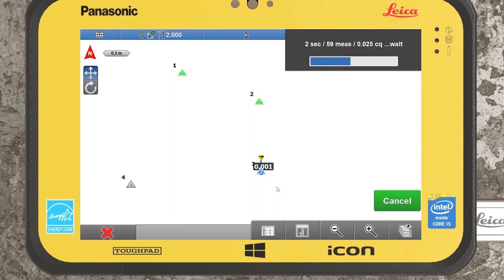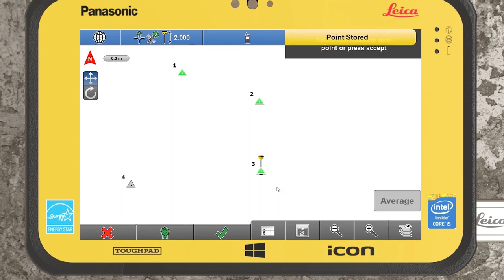And again, you're not limited to the number of control points you use. You'll always want to have good spread around your site, so good coverage. So if I have a rectangular site, I would traditionally want to have one in each corner, over the sides, and possibly in the center. What you can imagine is almost like a sheet.